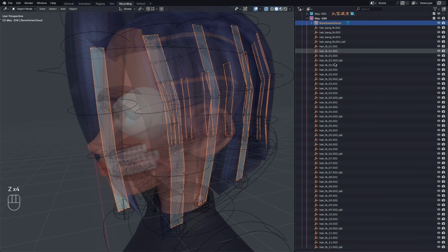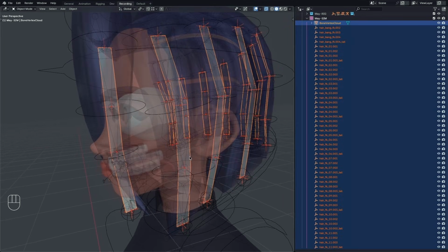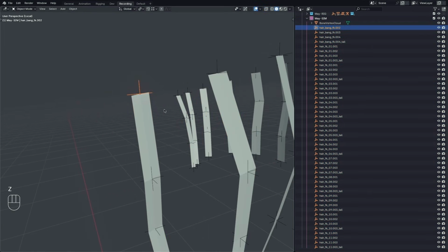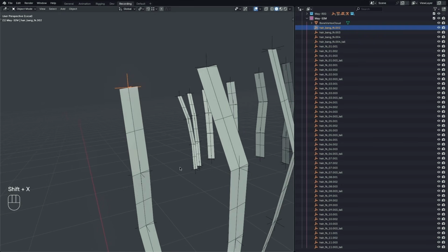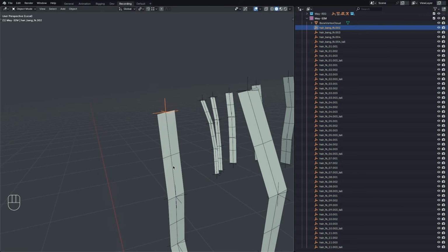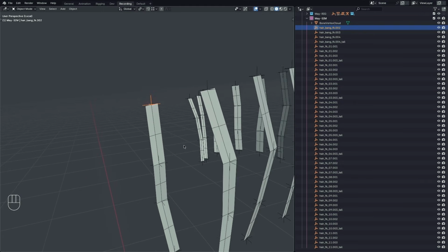Okay, so now let's parent these empties to our mesh object that we created. So I'm going to select all of this here, hold shift, all of these objects, and then I'm going to hit slash to isolate them. So essentially these empties are acting as sort of intermediary objects because you can't quite constrain bones directly to vertices or have them follow along with vertices on mesh objects, at least at this point in time in Blender. In the future, there might be some geometry node tools that come along that make that easier, but at the moment, we're just going to use these empties as sort of intermediaries to allow our claw simulation to drive our bones.